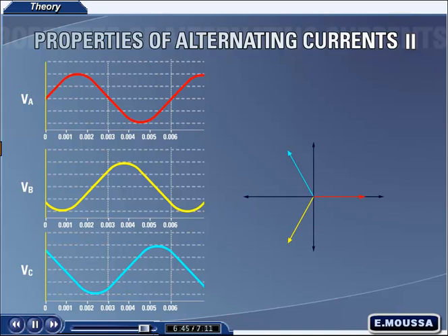The 120-degree phase displacement of the output voltages can be represented by joining the vectors at one end and having an angle of 120 degrees between each vector as shown. An output phase sequence of ABC can be represented by the labeling and the convention that positive sequence currents rotate in a counterclockwise direction. The rotation of the vectors, phase A, B, and C, can be seen here. The vectors are rotating counterclockwise.